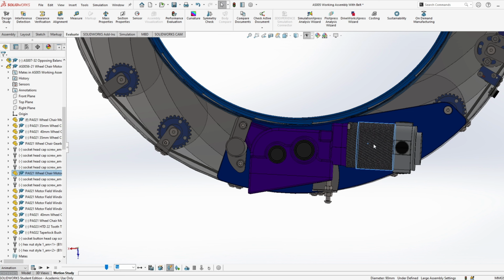So if I wanted to tension the belt, I would move the motor inwards towards the center of the aperture, and if I wanted to slacken or retract the belt, I would move the motor out this way, away from the center of the aperture.